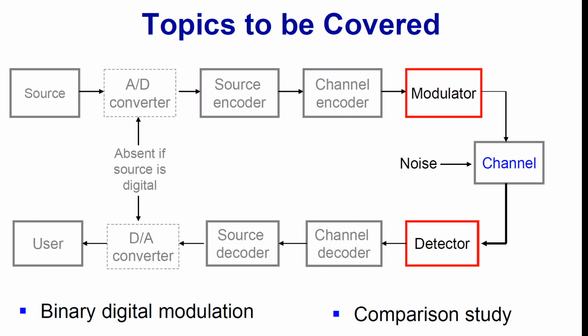So here we will use a carrier, and some property of the carrier is varied in accordance with our digital signal. The channel used for passband data transmission may be a microwave radio link, a satellite channel, or the like. The rule is, if you are having a wired communication, you can use baseband data transmission, transmitting a pulse directly. And if you are using a wireless channel, where there is no direct connection between source and receiver, then you need to use passband data transmission.